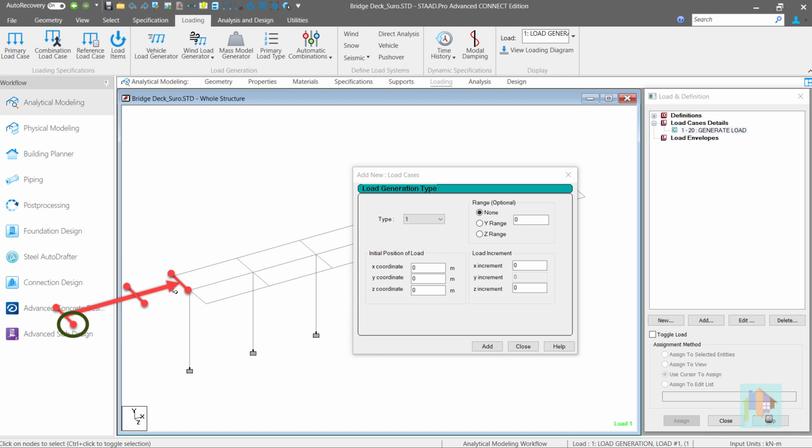If the front left wheel is placed at this corner node, then its coordinate is 0, 0, and coordinate of this reference point is -8, 1.8. X is in negative direction and Z in positive direction. It is not very complicated. First, we need to fix the front wheel location, get the coordinate, then we can calculate the coordinate of reference point using simple geometry and vehicle dimension.